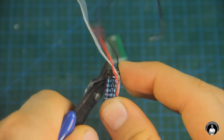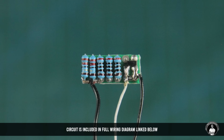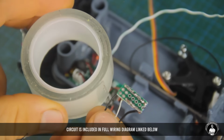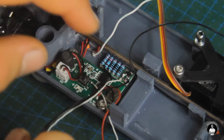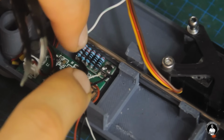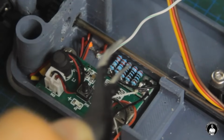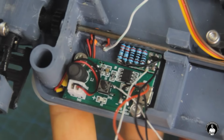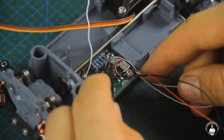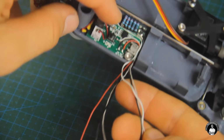After trimming the board, it should look more or less like this. Here's a good reference image to clearly see the connections. The LED control board can then be double-sided taped to the chassis and have the cathode LED wire soldered on board. After a bit of wire management, we should have 3 wires sticking out from the LED board and 3 from